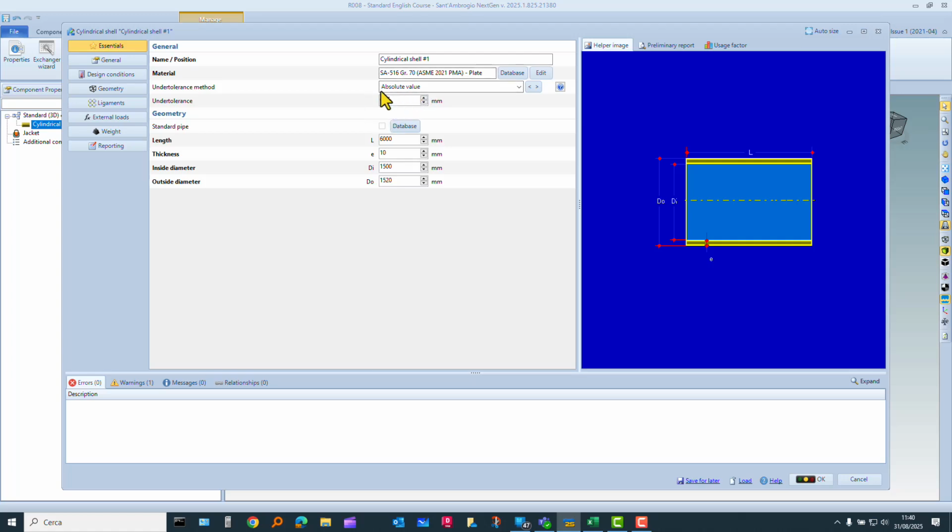In this case, the thickness has to be considered. The thickness given by the standard is 0.25 millimeter. Note the small note here, PMA, Particular Material Appraisal. What is the meaning of this note? That it is necessary to have from the material manufacturer the assurance or the guarantee that the hot tensile properties considered by the ASME code are acceptable for him, and so he is able to guarantee these hot tensile properties.